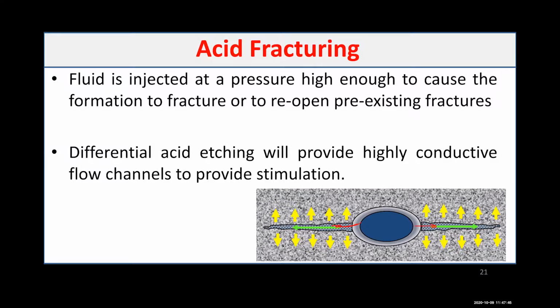with acid. You are not pumping acid in another direction anymore. What's happening as soon as you create the frac, all the acid will go toward the fracture. The acid will start to react with the fracture's face and create an uneven pattern. So when you close, the uneven pattern will create a permeability that is big enough to have the flow through it.